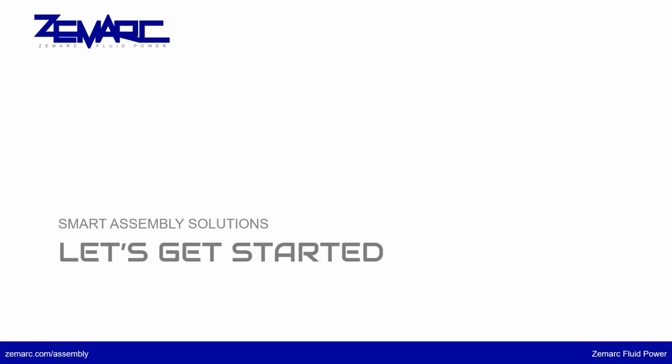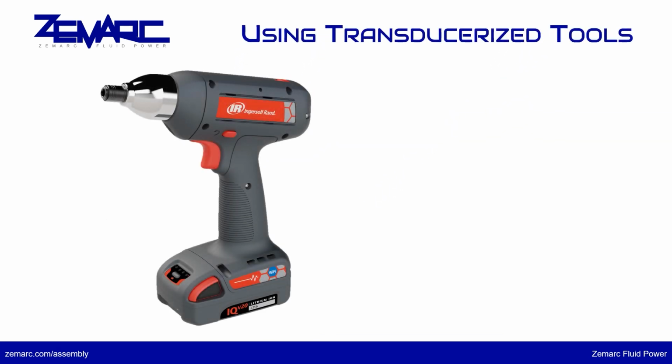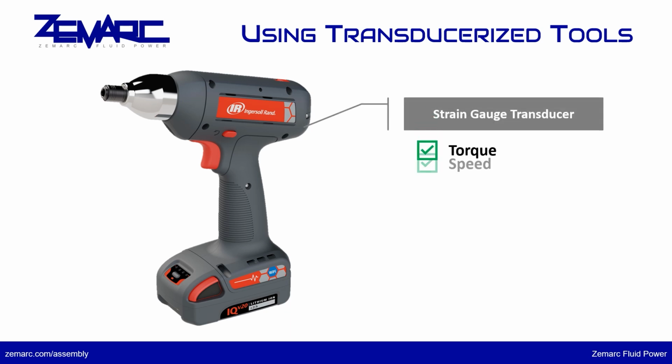And on that note, let's get started on the core concepts to error-proofing your manufacturing process with precision fastening and smart assembly solutions. We're going to kick off today by exploring Ingersoll Rand's QX series. These are cordless transducerized tools, which means they contain a strain gauge transducer built into the spindle, which in their simplest form allows you to capture trace data, control torque, speed, and total degrees of rotation. But the best part about a transducer is that it really grants you access to taking on a full plant integration approach, with Pico MES included.